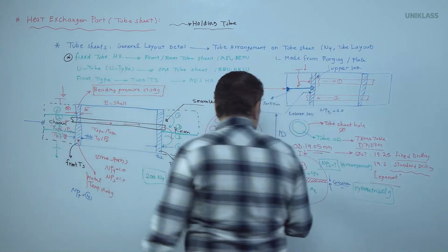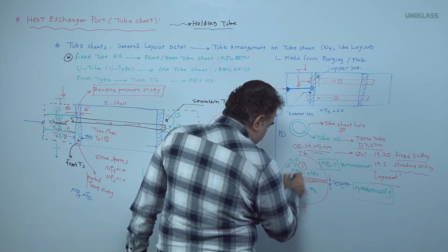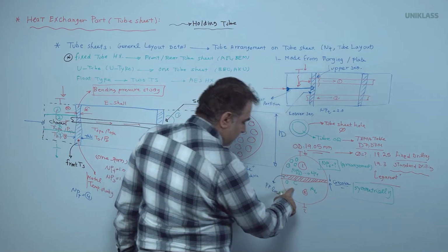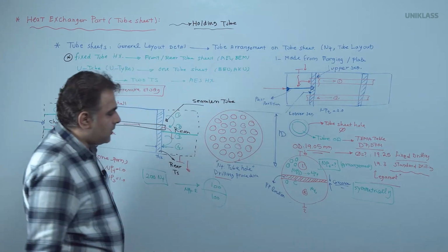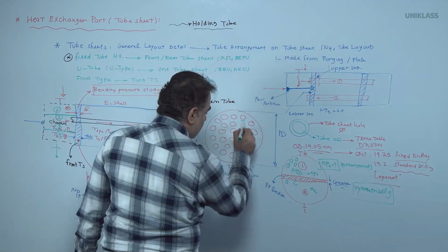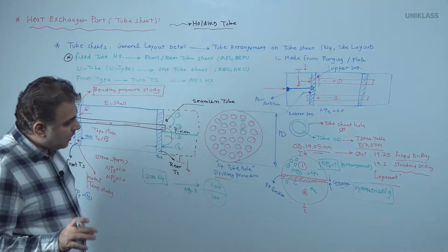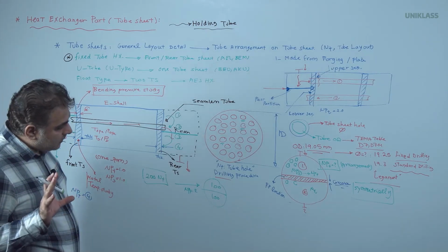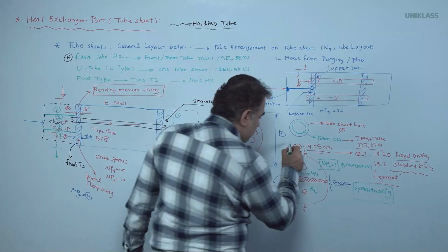Therefore, this tube sheet layout and arrangement is available for, for example, 100 tubes. Every tube in the top shall be the same in the bottom. That is the symmetrical tube. It is forbidden to use two different heat exchanger OD, even for special items. We are not talking about the special item. The TEMA standard says to us, please use one standard tube as a reference.